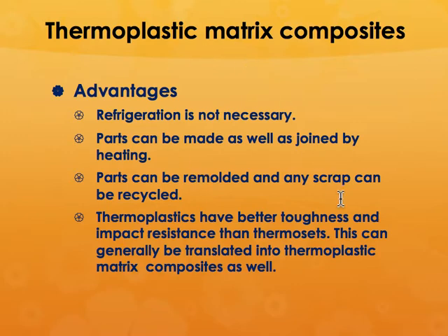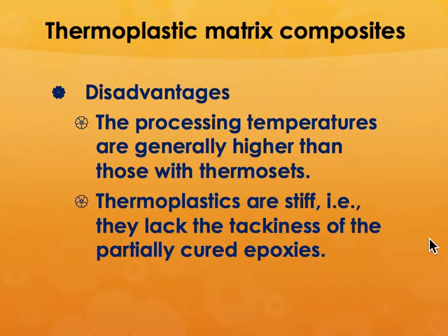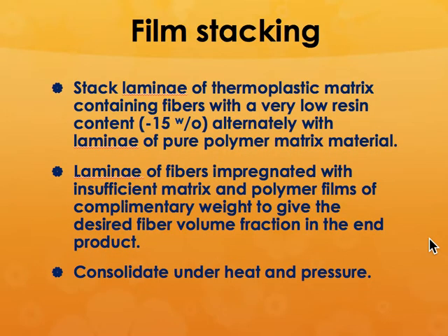Now, the other advantage with thermoplastics is better recyclability. But they also have higher processing temperatures needed for making these composite materials. And they are pretty stiff and they lack the tackiness of partially cured epoxies. And the other disadvantage is that they are typically more expensive than thermoset type of materials.